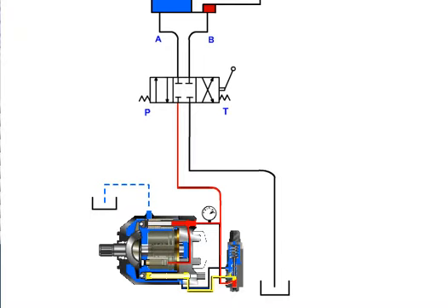to a vertical position. When the swash plate is vertical, the pump is now at zero stroke or no flow, and the pressure at the outlet port is maintained at the set pressure. A very slight amount of flow is produced to lubricate the pump and maintain compensated pressure. This flow is vented through the pump case drain port.